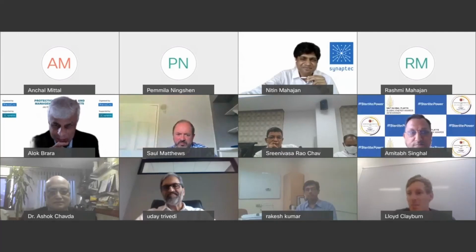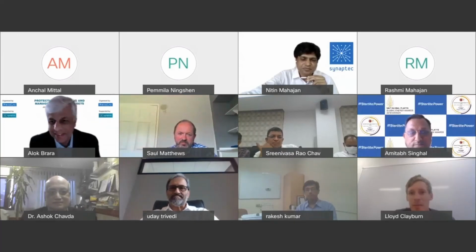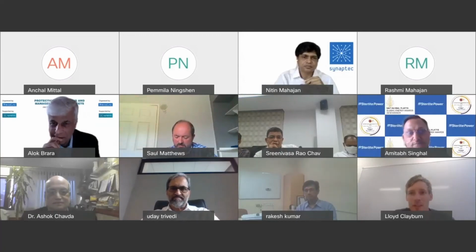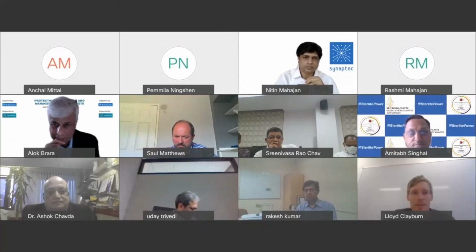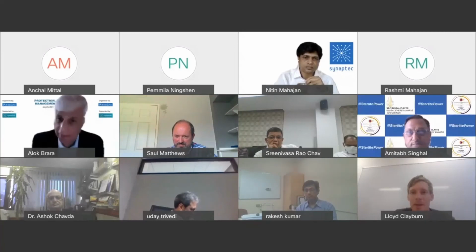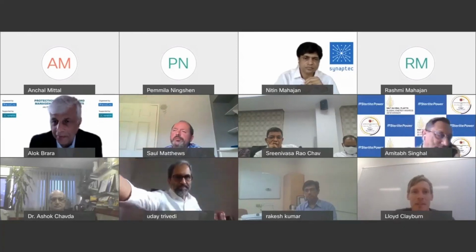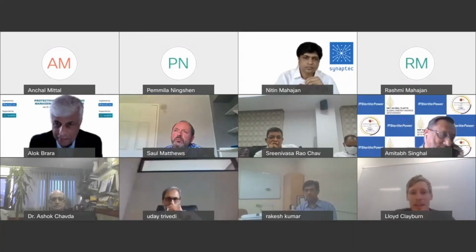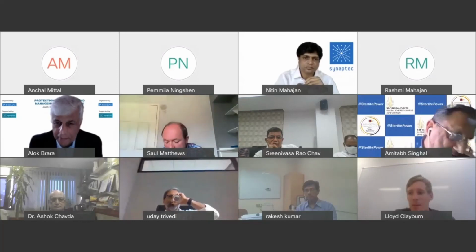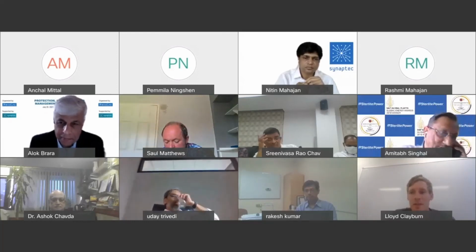Yeah, I'd like to just quickly highlight that, although it's not asset monitoring directly, we can also feed our measurements into dynamic line rating systems. That helps in itself to maximize the current that you can put down lines, and it prevents you from having to replace those lines. So it is a way to extend asset life.